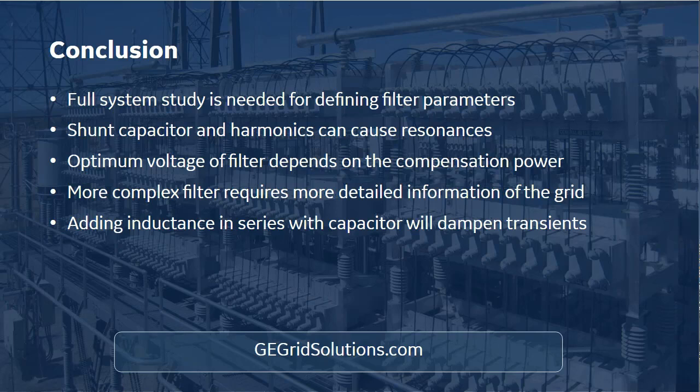And then if you have a very small compensation power requirement, let's say up to 450 kilowatts, this can also be made with low voltage capacitors. But here, the feeder for these low voltage capacitors is the limiting factor because the fuses have to be very big. So it's not really practical to have more than 450 kilowatts with low voltage. Everything beyond that typically has to be medium voltage.